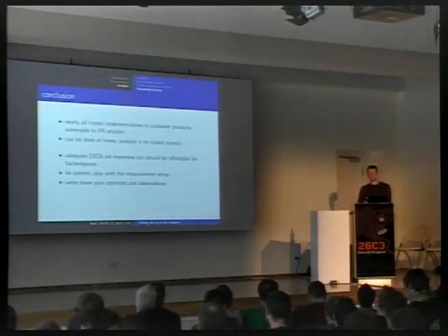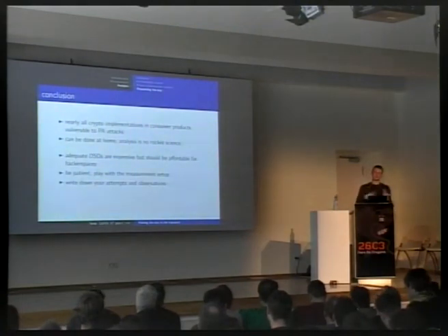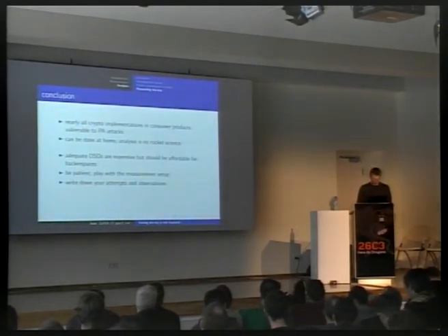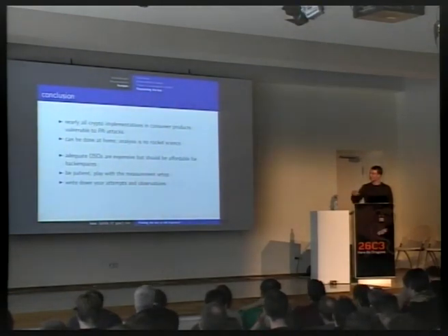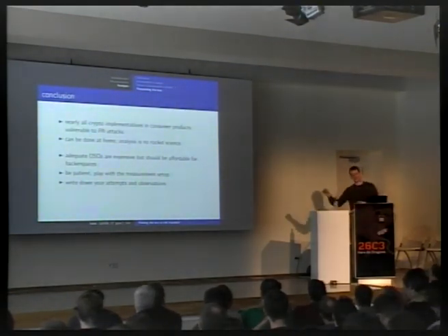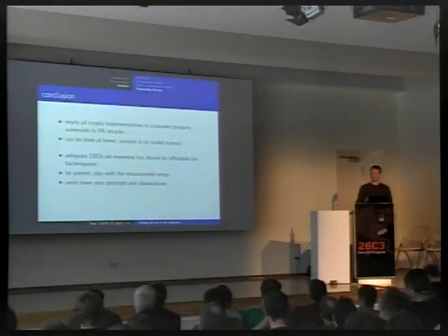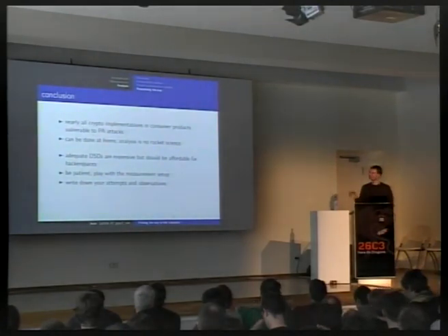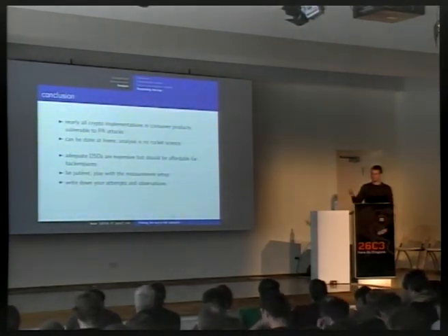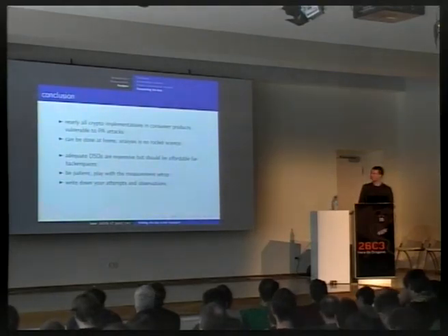You have to play with the measurement setup, find noise, reduce noise, try some other parameters, try another resistor, and so on. You'll find a lot of fault sources you have to remove before going on. And the best way to not have to remove this fault again is writing it down if you see it. So if you change anything, a resistor or whatever, a setting, write it down and also write down your observations. Otherwise, you will do the same thing again if you have another device or setting.